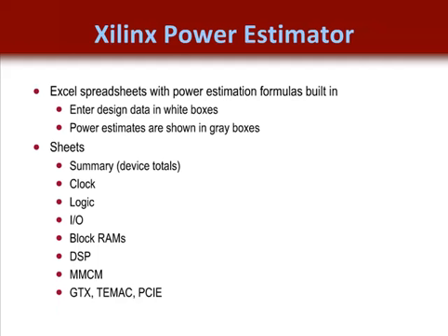Now this slide is trying to highlight some of the benefits of the dedicated hardware resources that exist in the newest FPGAs. The most useful of the dedicated hardware resources is the DSP slice and the block RAM resources. Besides using less power and saving primary FPGA resources, that is, LUTs and registers, using these dedicated resources makes it easier to estimate your timing. This is because the architecture delays of the dedicated resources are known before place and route is completed.